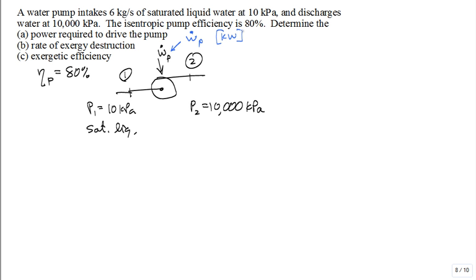How do I want to do this? You have the isentropic efficiency, so you just manipulate it to solve. So the isentropic efficiency of the pump is a ratio of 2 works per unit mass. One is smaller, put that in the numerator. One is larger, put that in the denominator. The work isentropic compared to the work actual. The work per unit mass isentropic compared to the work per unit mass actual.